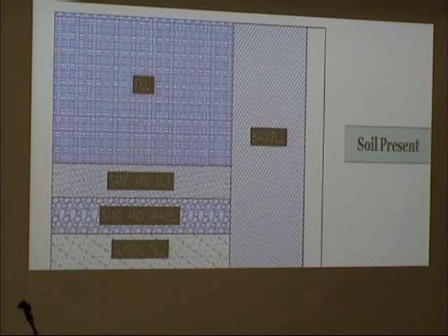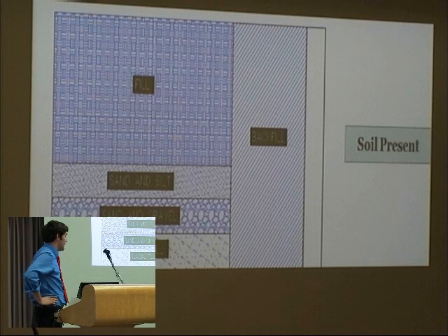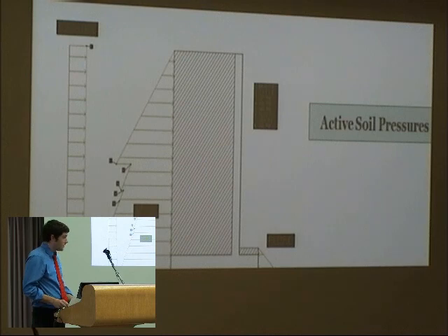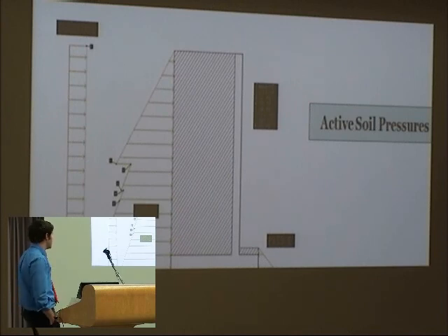to install a shear key, which you actually can't see. It's at the bottom of this figure. This allowed us to get passive resistance from the railroad side of the abutment. And here you can see the active and passive earth pressures, as well as the surcharge due to construction equipment on site during the installment of the abutment.